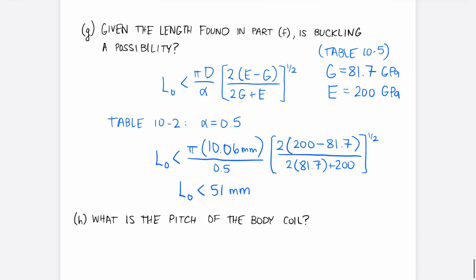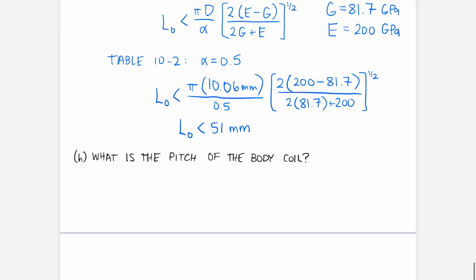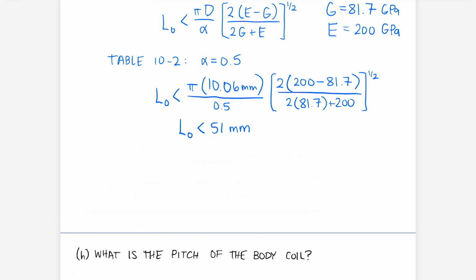The other thing that we can do is place an inside rod into the middle of our spring. This is something we didn't talk about much when we were discussing buckling. But one easy precaution to take to help avoid buckling is to simply place a rod through the center of the spring, so that if the spring does want to buckle, it's going to actually contact this inside rod.